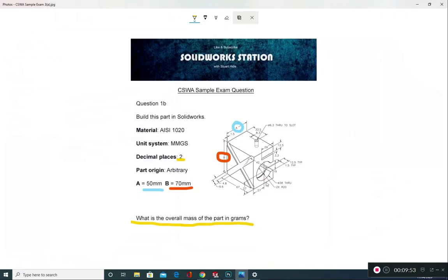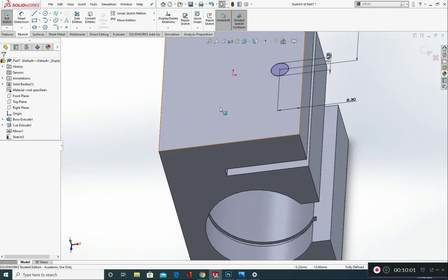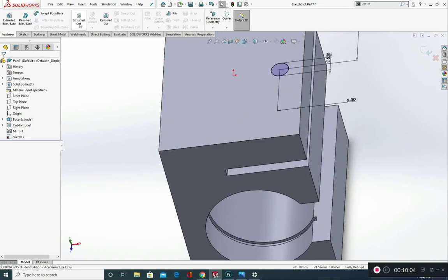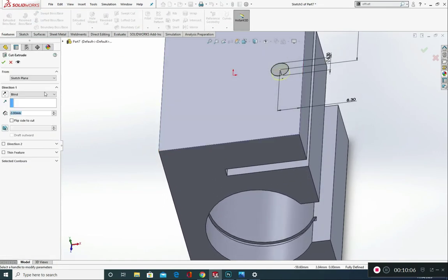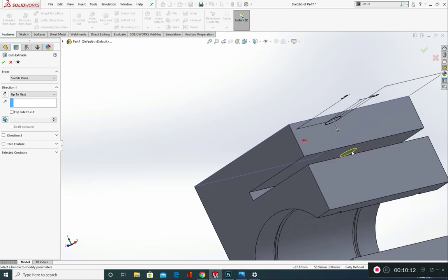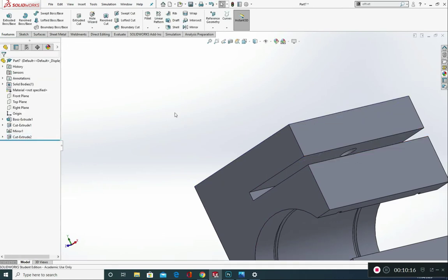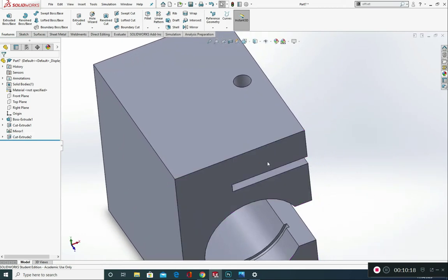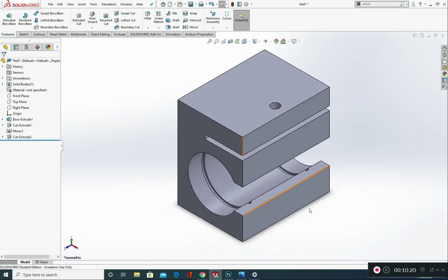Now on the drawing it's actually specifying 6.3mm through to the slot, this being the slot. So when we go into SolidWorks and we're saying Features, Extruded Cut, we can't say blind or through all on this. We're going to have to say probably up to next, like so, and green tick. Okay, Control 7 on your keyboard and you'll get a nice isometric view.